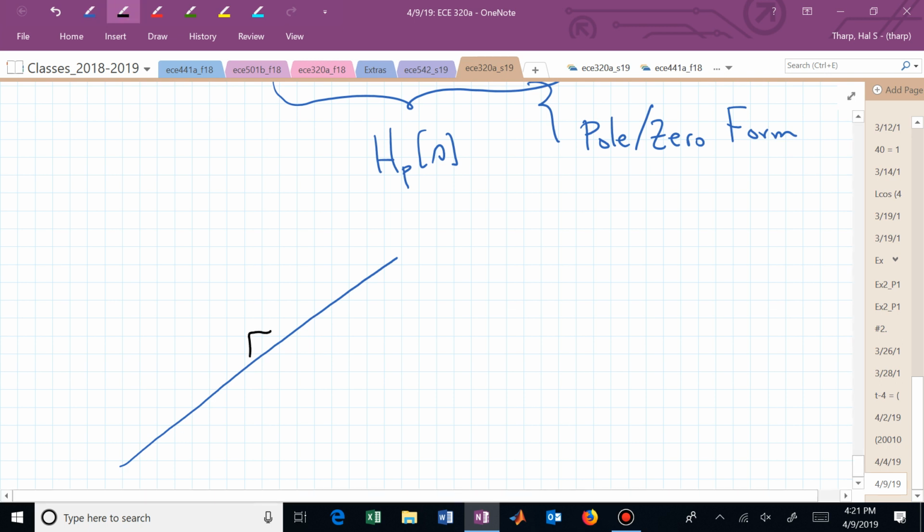We have one factor that we're coming up from the bottom from, and what's our slope when we just have one linear factor? What's that magic number? One of the magic numbers. Let's do it in decades. It's plus 20 dB per decade. So this is now going up at plus 20 dB per decade.